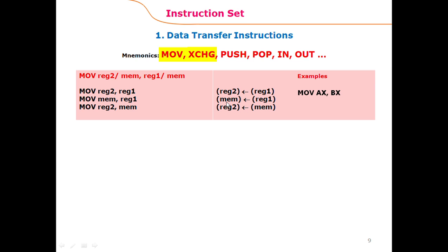And this memory location can be defined in different ways, using different memory addressing modes. For example, there is a move instruction where 1234H, the H means hexadecimal. And the brackets mean that this value is not data, but it is an address. An offset address is provided here. So this instruction would move 16-bit content from this BX register to a memory location in the data segment defined by this offset address. So the offset address 1234H is added to the left-shifted value from the data segment register, and a physical address or memory address is calculated. And the 16-bit value is stored on that location plus the next higher location.